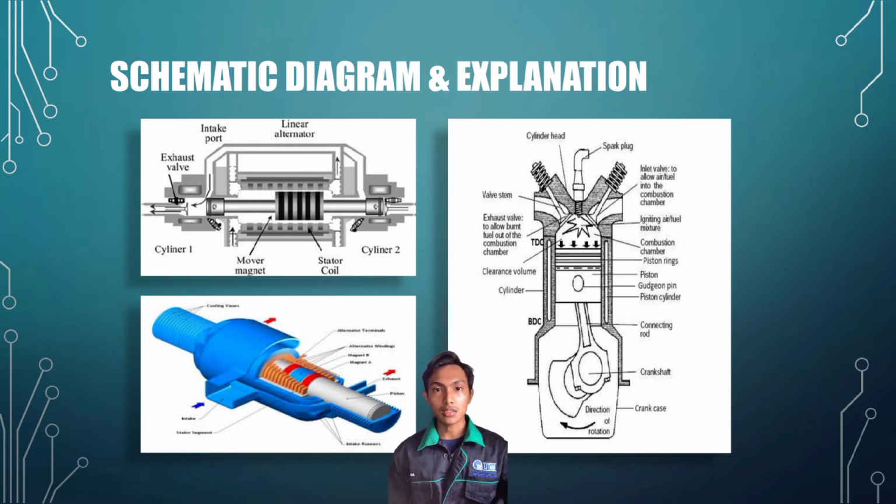Combustion occurs alternately at each end of the piston, and a modern two-stroke cycle scavenging process is used. The alternator component controls the piston motion and thus the extent of cylinder gas compression by efficiently managing the piston's kinetic energy through each stroke. Compression of the fuel or admixture is achieved initially, and as a result, a mechanically simple variable compression ratio design is possible with sophisticated electronic control.